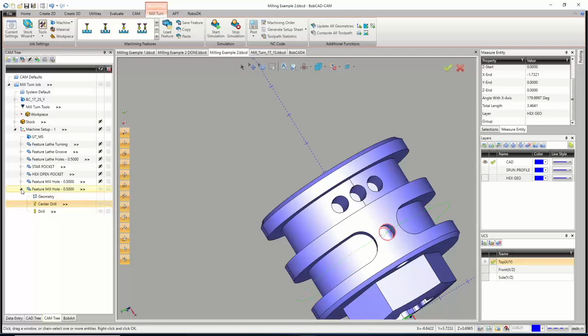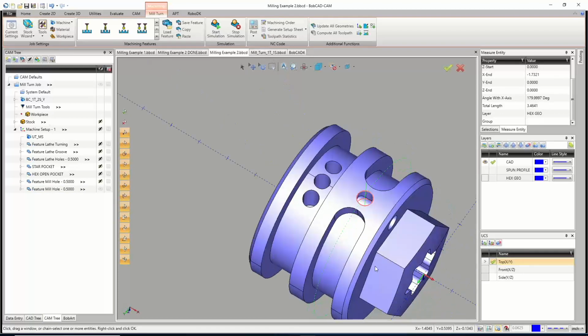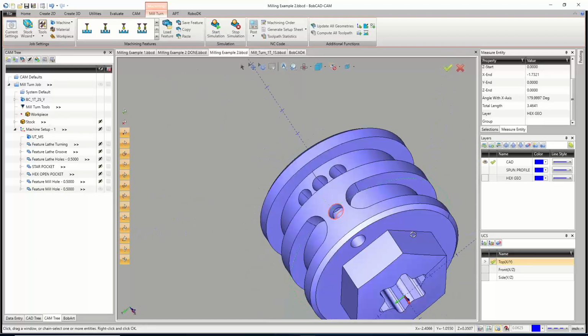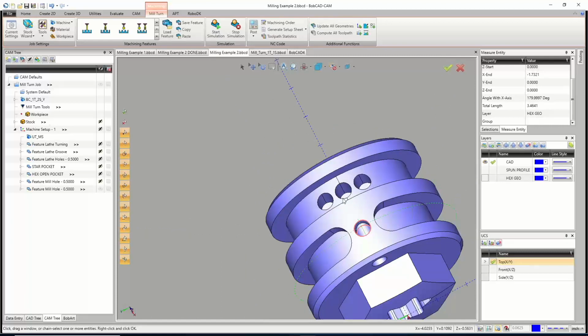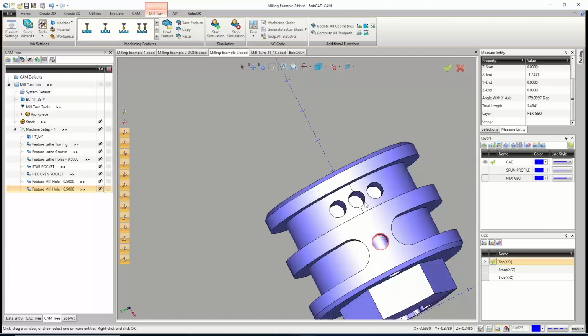So for us to do that one, we want to do an index system first. So I want the part to orient to the center of this and then kind of drill all 3 holes. Now this is a perfect part that I made it this way. So it's kind of a perfect world scenario where I have a surface in the bottom of those holes that's flat. And that's what we need if we're going to define an index system.